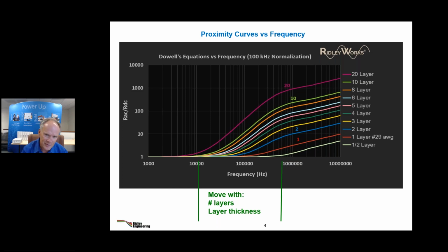And now you've got this horrendous convolution of the solution to Dowell's equations, which are bad enough, but then you've got to extract the Fourier transform of the waveform of the converter that you're on, and every converter is different. So if you want to see that done in all of its gory detail, you go get the book by Professor Hurley. I do recommend you get that.